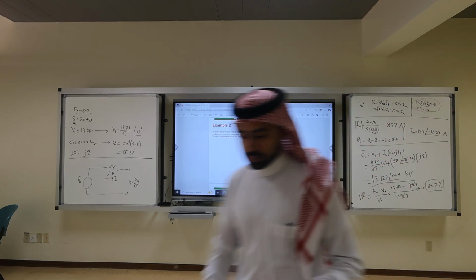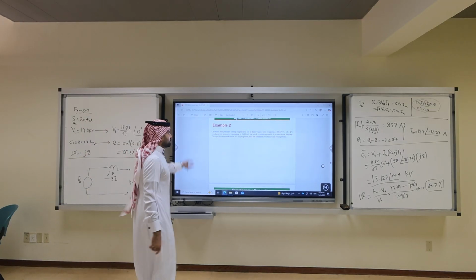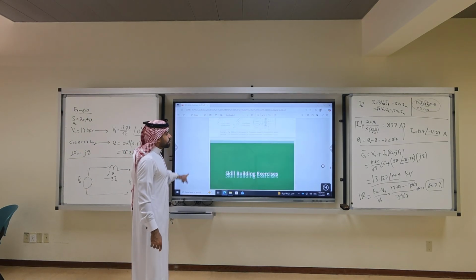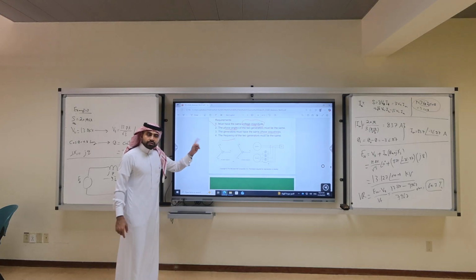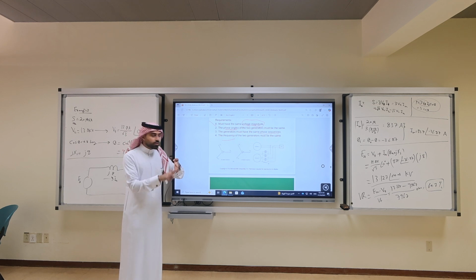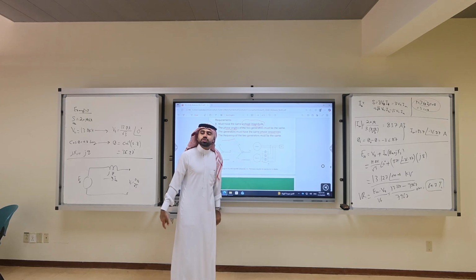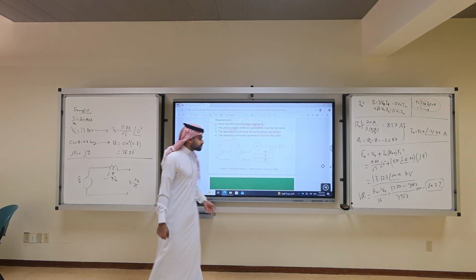Okay? Let's do. You remember a parallel operation? Don't forget the four conditions: same voltage, phase angle, same phase sequence, same frequency. These are lamps. If these lamps are connected, it means parallel operation is on. Clear?